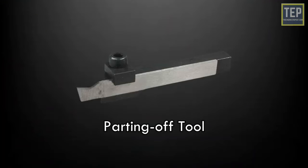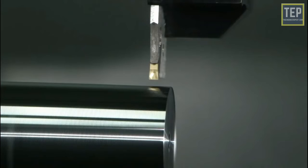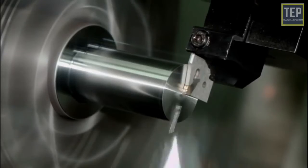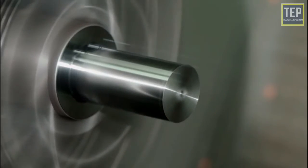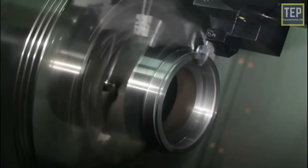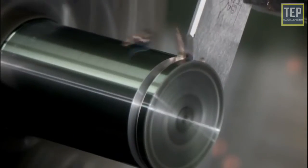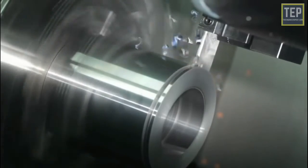Parting off tool. A parting off tool is normally forged and used as bits for cemented carbide tipped tools. A parting off tool is made as narrow as possible to remove the minimum of metal. As the tool cuts deep into the work, clearance is provided all around the tool cutting edge to prevent it from rubbing against the work surface. The tool is purely end cutting. It has no side rake. Slight back rake is provided on the tool to promote an easy flow of the chips.